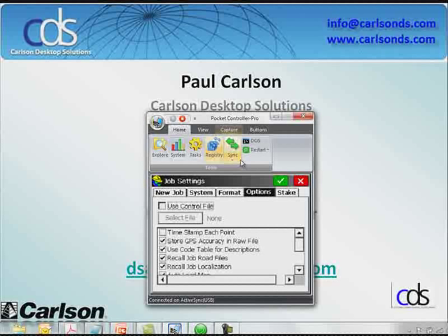Now, there's a lot of information in the GPS vectors. I am not a geodesist. I don't claim to be. I'm one of the least intelligent people that I know, so I'm not an expert here to tell you line by line what this information is. But essentially, when I look at this inside the RW5 file, I'm seeing the base position, the deltas. Right above that, I'm seeing the date and the GPS clock time that point was started. Below that, you'll see the TM note. That is SurvCE's timestamp. That appears if you have turned the time stamping on back under the main settings.